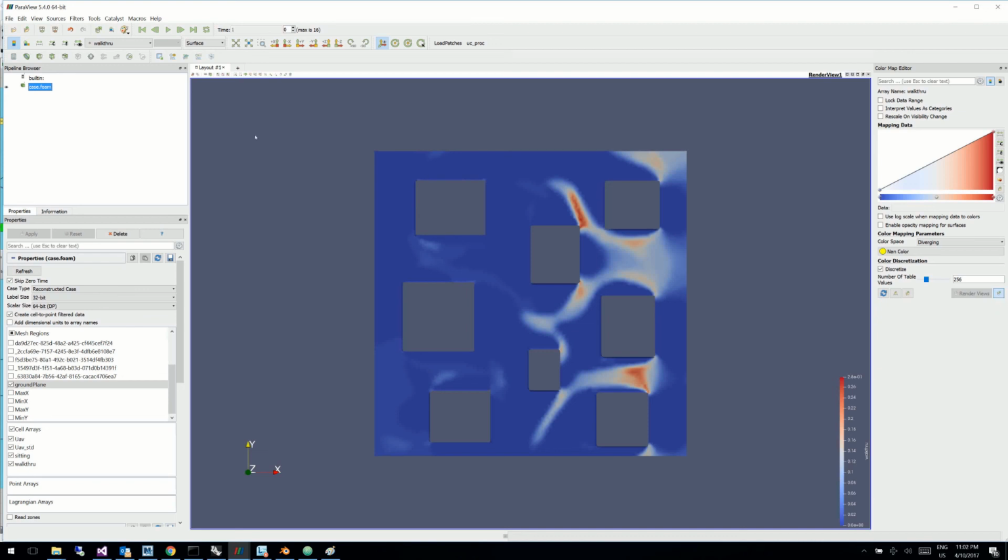So now what we want to do is turn these sitting and walk-through thresholds, which I really should have called Beaufort 3, Beaufort 4, but mostly 8 meters per second corresponds to walk-through and 5.5 corresponds to sitting and standing, so that's why I use those labels. But we want to turn these threshold values into a comfort map. So the way that we're going to do that is we use the calculator tool.